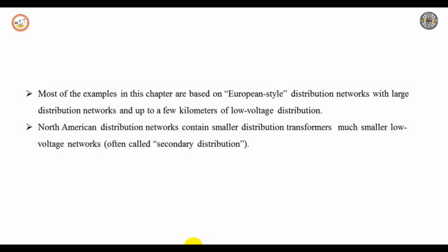A voltage drop of 10% results in a 10 to 15% increase in the load current drawn by induction motors, a decrease in starting torque of nearly 19%, and an increase in line losses in the distributor of about 20%.